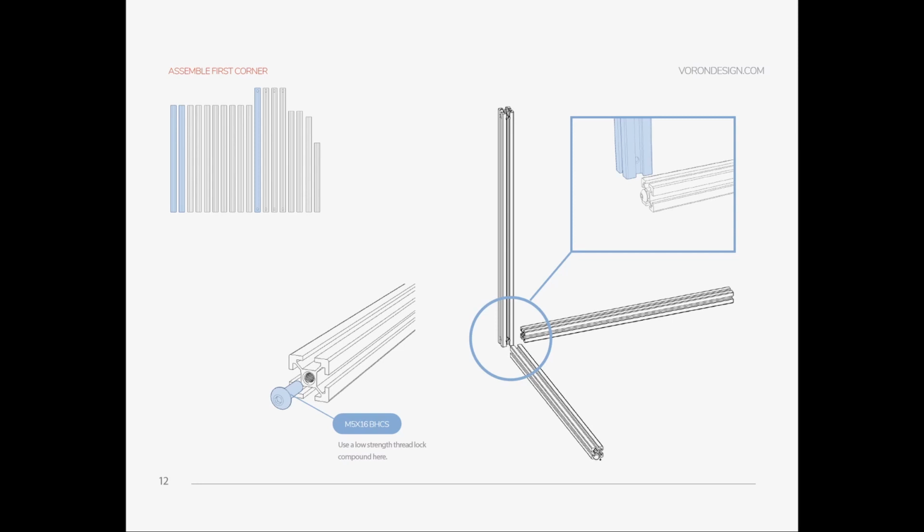So when you tighten your screw, your extrusion will tend to move to the left a little bit, and you will have 95 degrees. Actually we are aiming for 90 degrees, so it will not be square. While you are putting them together, you should use a flat surface.